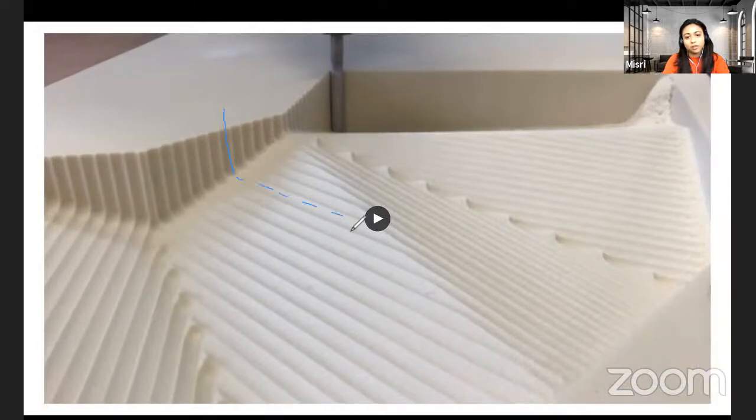It goes in and follows this geometry, and then it exits out, which essentially means you're left with corner conditions like these, which is why we went back and modeled out another tool path, which was simply like the contour operation we just saw, where the tool simply goes and cleans all the rough edges up so that you have a finished product.